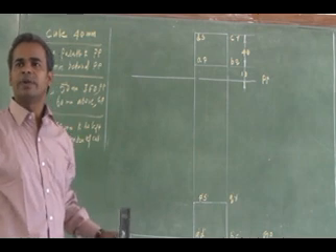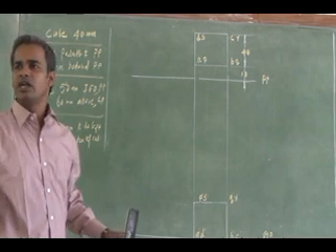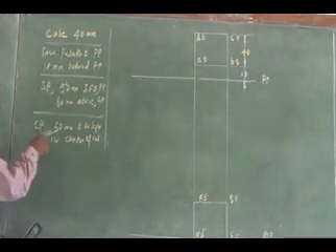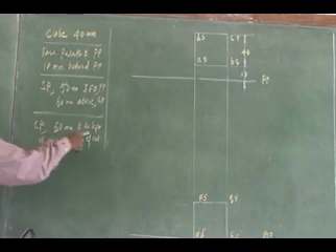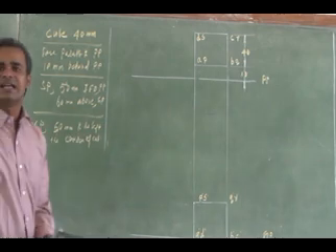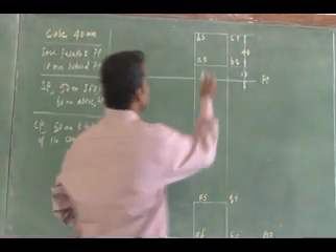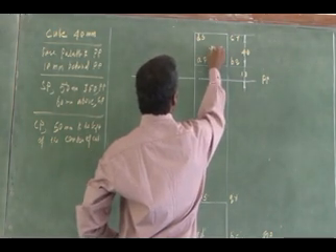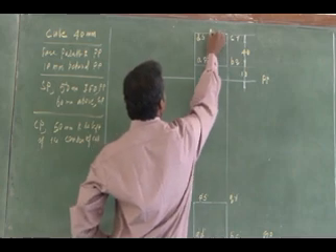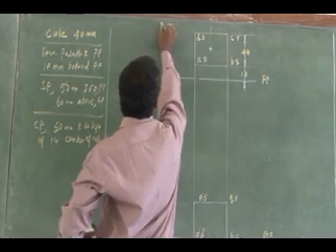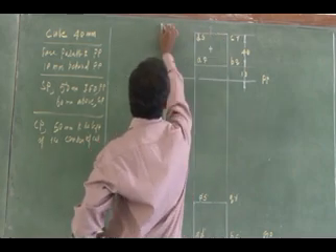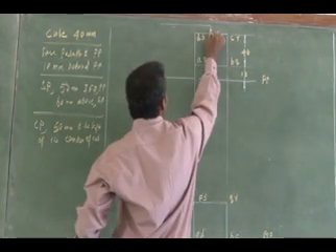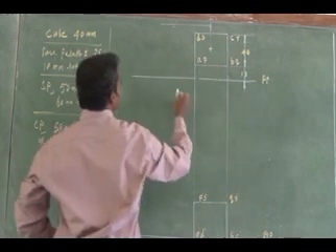Listen, one more thing I have to represent. What is that? The station point, which is going to be on the center plane. It is given. The center plane is 50 mm to the left of the center of the cube, right? So which is the center of the cube? The cube center is this. You mark the cube center. So from here, measure 50 mm to the left. Right? From here, you measure 50 mm to the left.